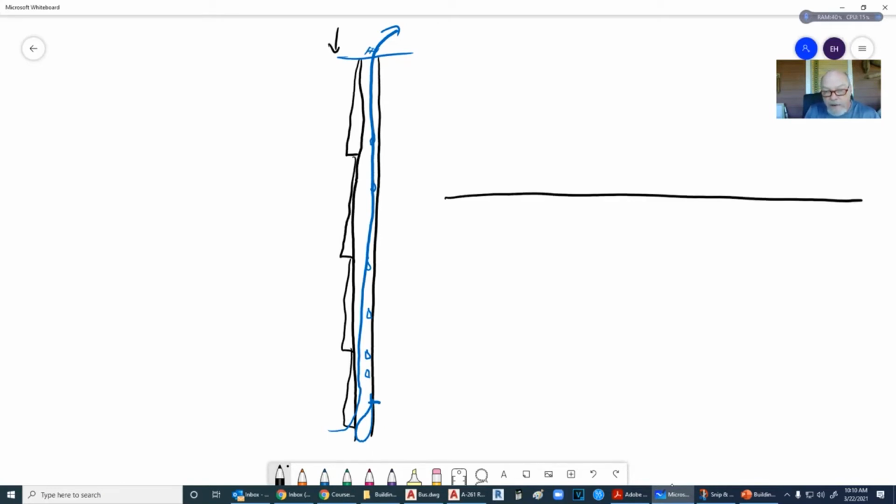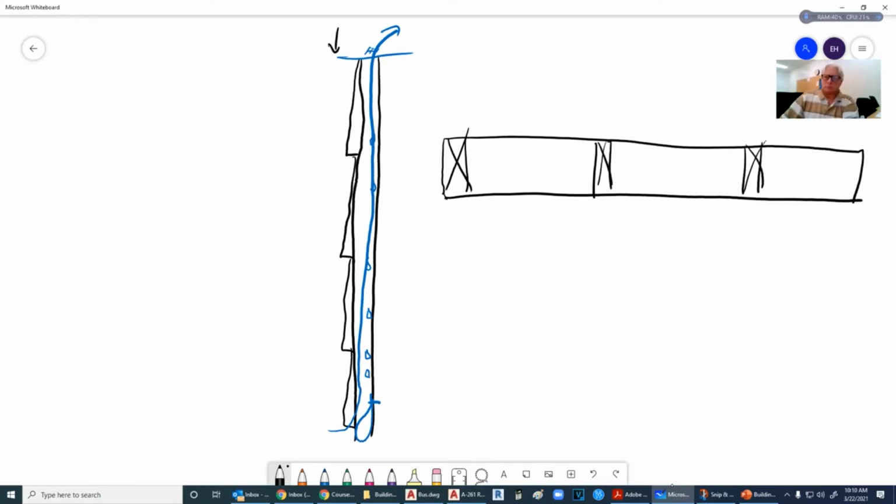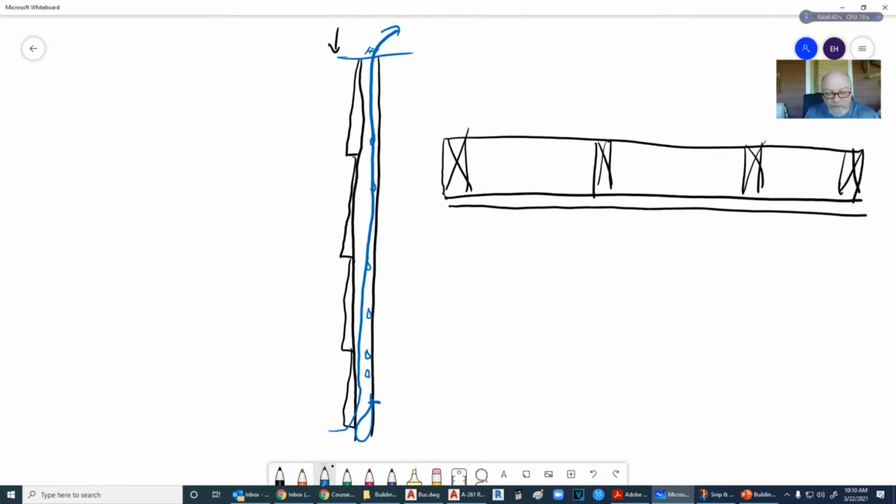Here is my, we'll just draw the studs and everything. Here's my stud wall. Got my studs in there, 2x4 either. And then I'm going to use extruded polystyrene on here so that I get maximum insulation through here. Then I'm going to put these strips on there. So again, they're like a half an inch thick by 1.5 inches wide. And I'm going to nail these on here with my framing nailer.